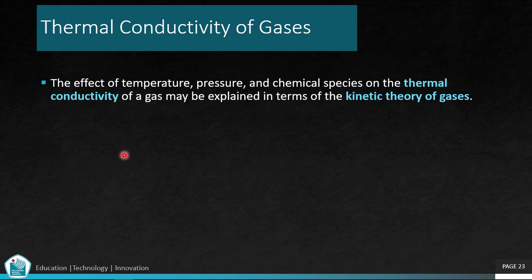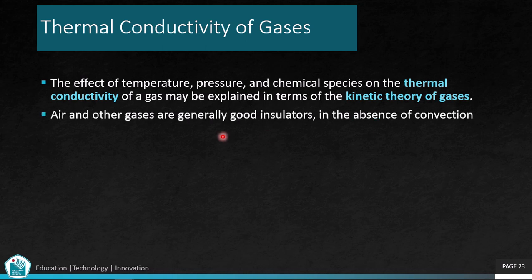And then the thermal conductivity of gases and liquids is generally smaller than that of solids. In the case of gases, the effect of temperature, pressure, and chemical species on the thermal conductivity may be explained in terms of the kinetic theory of gases. Air and other gases are generally good insulators in the absence of convection.